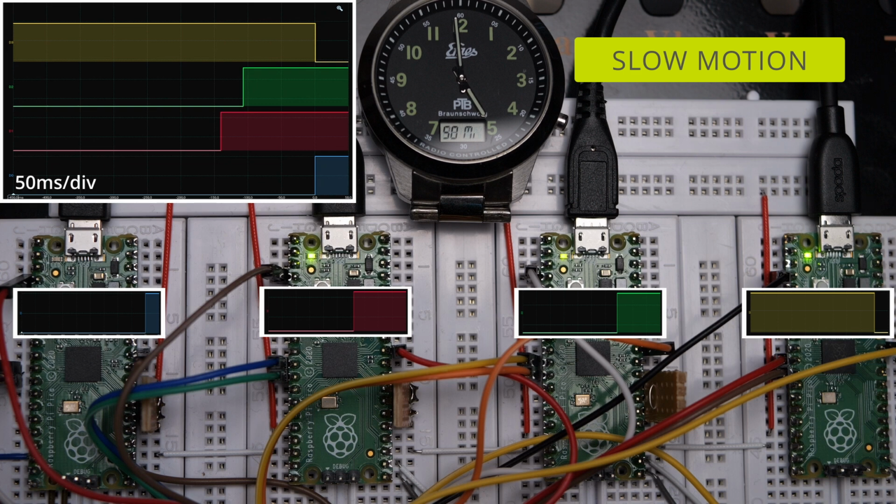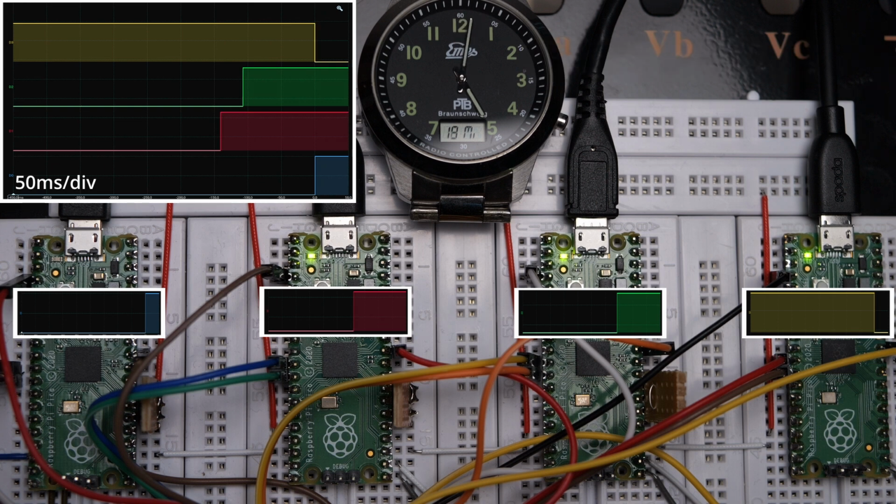Since the LED is turned on by software for 500 milliseconds, this deviation over 30 hours works out to 4.6 ppm clock rate difference between the leftmost and rightmost Pico. This is a typical result for general purpose crystals, even when operating at the same temperature as in this setup. Any temperature difference between the Picos would make the impact of the problem much larger.